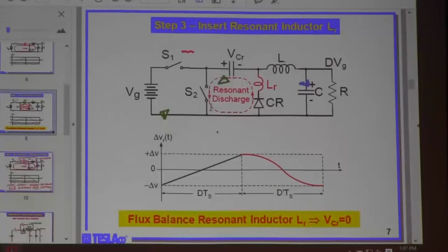What happened when I grounded the switch? I cut this connection, and if I put it down into the output, what happened? I get a free path for the discharge current. Yes, it is discharging, but it's discharging to the output. Bad news, I can't do an isolation transformer anymore here, because I cannot split the capacitor into two to get isolation, because it's now connecting this switch from the primary to the secondary side. But, hey, I'll first investigate what I can do with the non-isolated converters, right?